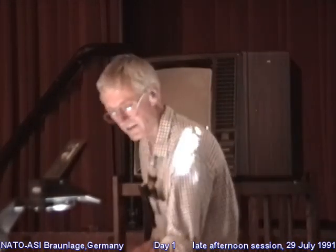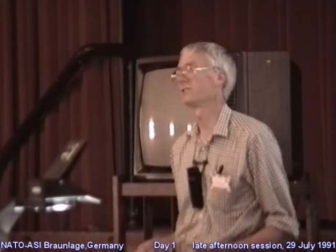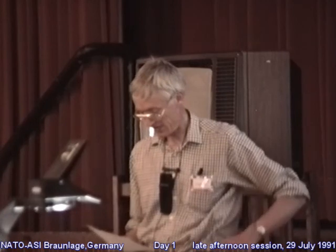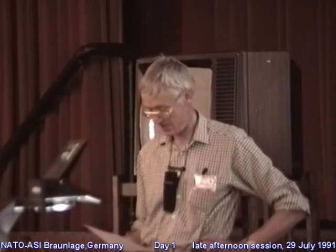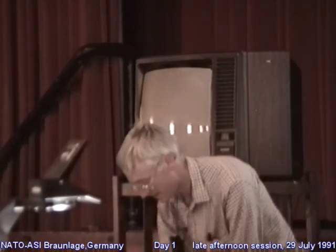We need to define an effective force of attraction. Just as an external load is minus the differential of potential energy with respect to distance, we can define an effective force of attraction in terms of minus the differential of the relevant surface energy with respect to distance. There it is. This can replace the tensile stresses associated with intermolecular attraction at the edge for some purposes. So let's see if I can work out how it varies with area.